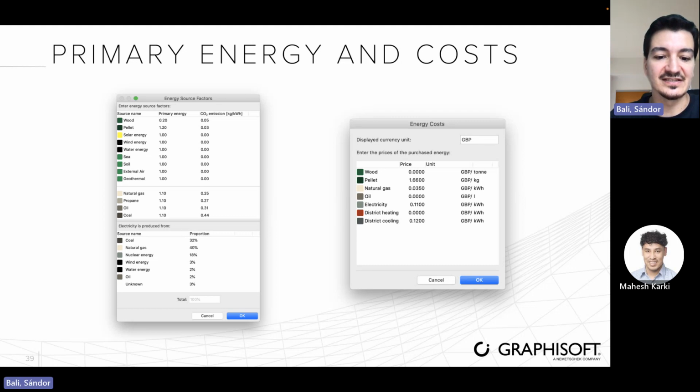These are going to be very interesting because for the primary energy factors, you will need to see what the losses are, what the inefficiencies in the system are. So typically, here, when you see that all these fossil fuels, the number is bigger than one, it means that there are losses. Whereas in case of wood, for example, it would be the other way around. This pellet, there should be a loss there actually, because that's not a fossil like that. So maybe this is a mistake here. But anyways, these are ratios or multipliers that relate to the amount of primary energy input, which is required to deliver 1 unit of useful energy to the end user.